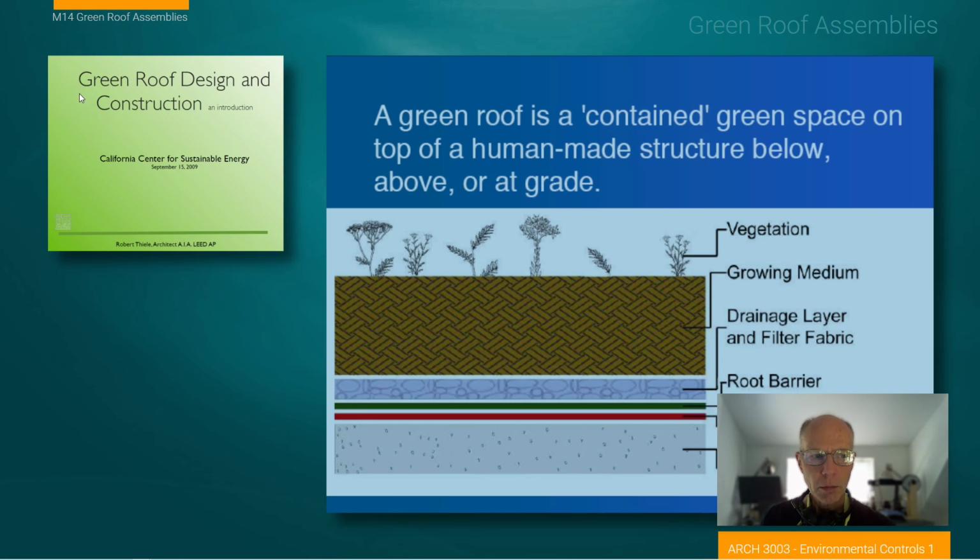So I've included some slides from this Green Roof Design and Construction Manual. It's from 2009, but I think it's pretty up to date, so to speak. Obviously, a cross-sectional roof to just get us started. We have our vegetation, our growing medium soil, and or other kinds of amended soils. We have an opportunity to manage what is placed in the soil composition to affect roof weight and moisture absorption.